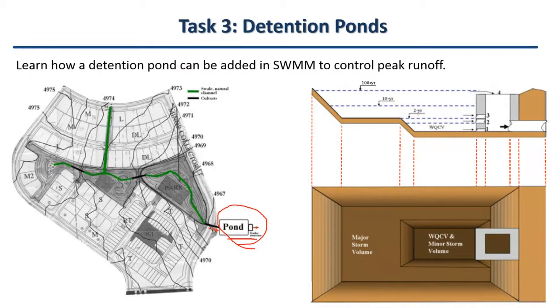The detention pond here can be used to discharge the flood with different return periods: 2 years, 10 years, and 100 years as well. And it's designed with this kind of level you can see here. This is for the water quality. This is a very small pond at the bottom. You can see here is a profile, and this is the cross section. Then later, the 2 years return period is happening in this section. Can you see here? 10 years with some levels in here.